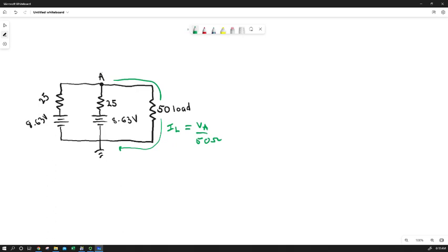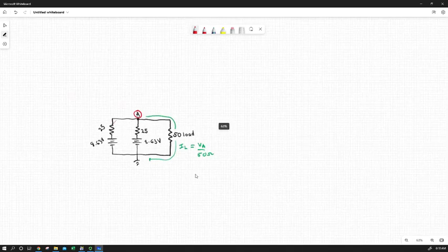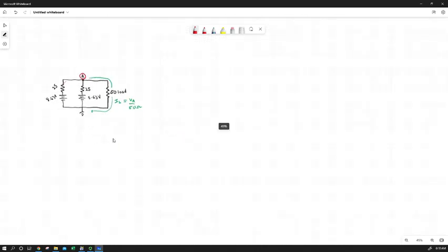The problem is, what is the voltage at A here? Because we have 2 sources, we don't know exactly what current is flowing out of this one, or is it flowing backwards. So in order to determine that, and again that's what our circuit simulator did behind the scenes for us with a push of a button, we're going to take the circuit apart and use a principle called superposition, which says that the actual currents flowing through each component and the voltages versus ground at every node in our circuit due to one source can be added to whatever those same things are due to another source.